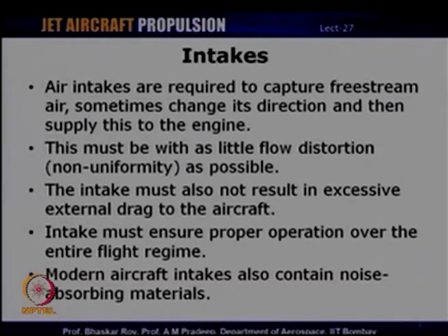And in some of the modern aircraft engines, intakes also have noise absorbing materials to shield the engine noise from reaching the fuselage. Especially in a transport aircraft, the nacelle that houses the engine, and that is also where the intake is molded, contains noise absorbing materials which can partially shield the engine noise from reaching the cabin. And so, that is another function. Of course, that is not really a function of the intake as such, but it is part of the nacelle which houses the engine, and it also forms a part of the intake.